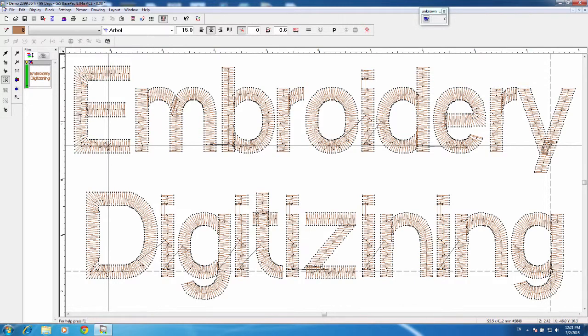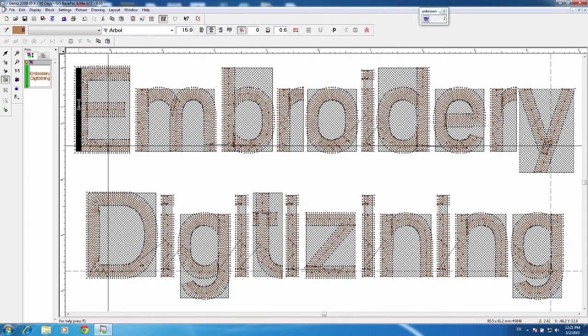The next option that is available is the constraints for a text line. We can give the lettering a maximum text length to follow, and it will actually compress the letters if it needs to. So let's go ahead and select all of our letters, and you can see that my cursor is blinking right here. Another easy way to select all the letters is the key combination Control and the letter A. When I use that, it selects all. Right now, with it not pressed in, there is no maximum text length, meaning that it's going to put it in the best fit line that it sees available.